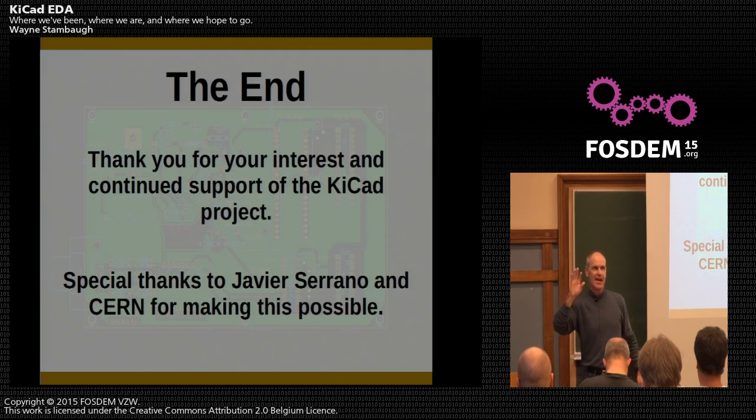I'm not 100% sure, but I know right now only the board. So if you import a board, it'll render in Pcbnew just like it would in Eagle. And when you save it, obviously we're not saving it back to Eagle, we're saving it to Pcbnew, our file format. But yes, the import is direct, and libraries as well.